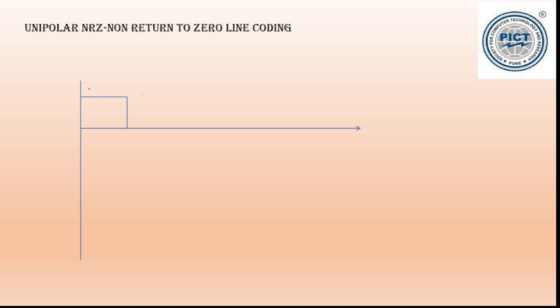So first two bits are 1 1, next bit is 0, then again 1, and this is 0 1 0, then last two are again 0 as nothing is mentioned. On the x axis this is time, so this is 1 1 0 1 0 1 0 1 0 0 bits we want to transfer from the transmitting end.